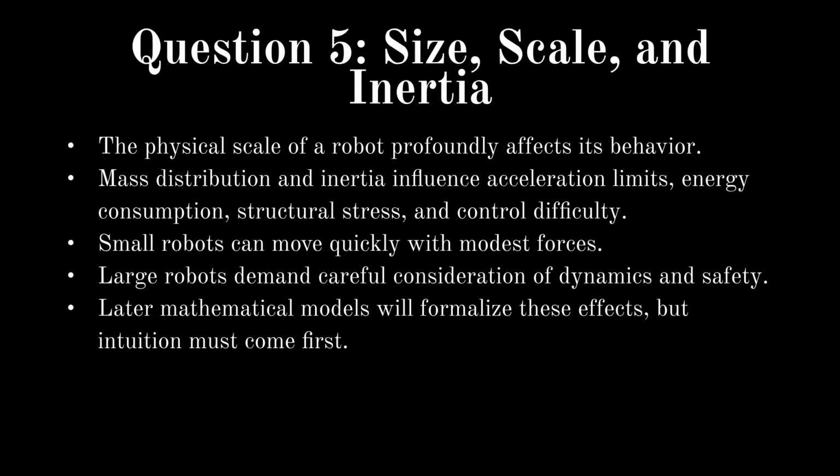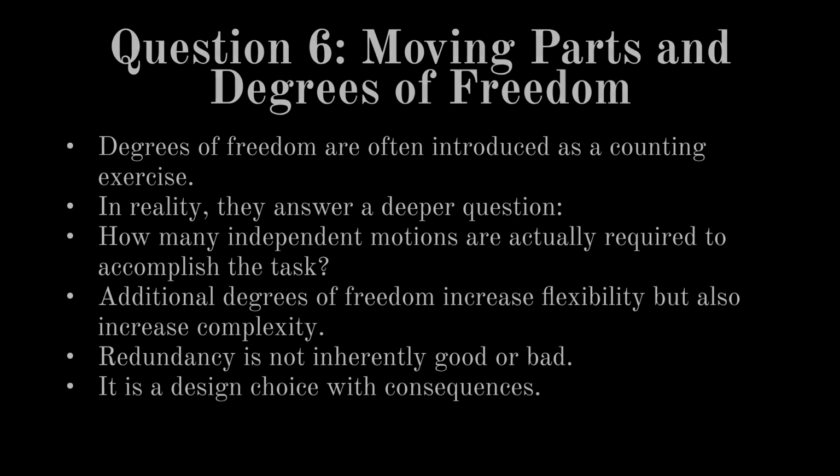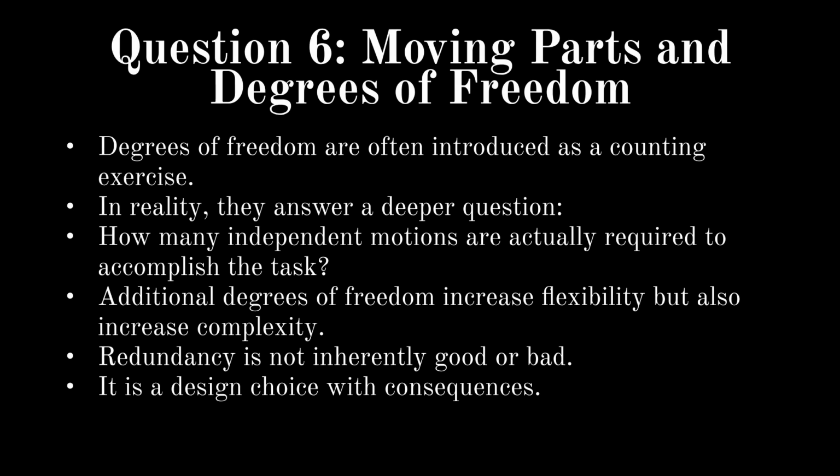Question 5. Size, scale, and inertia. A robot's physical scale affects acceleration limits, energy consumption, and structural stress. Small robots move quickly, while large robots require careful dynamic and safety considerations. Question 6. Moving parts and degrees of freedom. Degrees of freedom answer how many independent motions are required for the task. Increasing them adds complexity and flexibility. Redundancy is a conscious design choice with consequences.